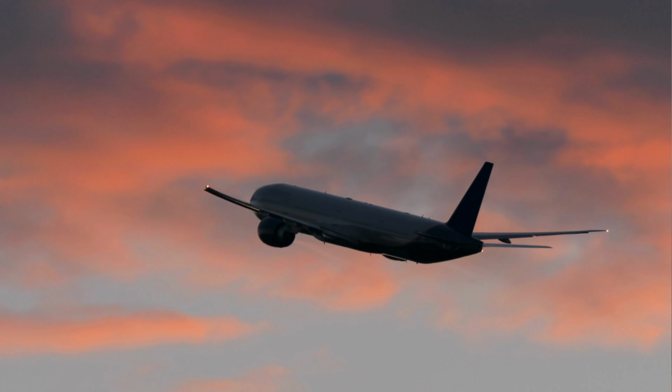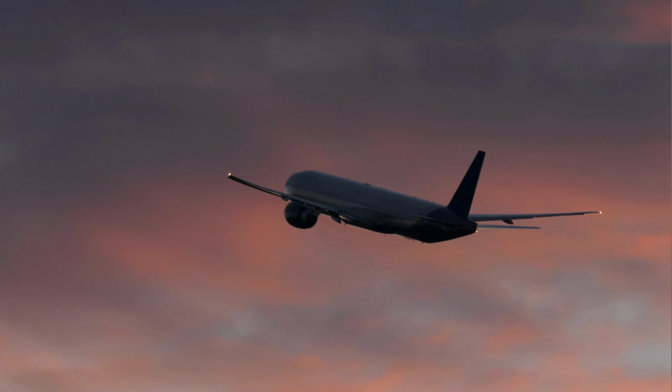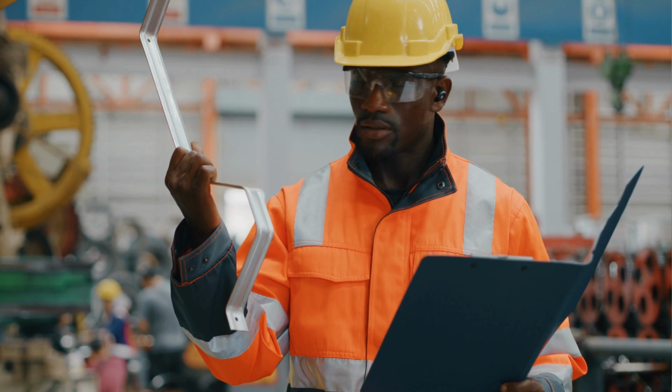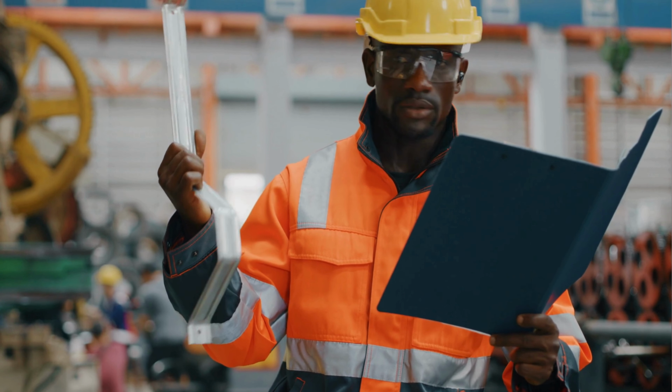But as long as you do your inspection, you verify that the storage conditions were proper, you ensure that you have the proper paperwork, you're good to go. Basically the part is airworthy. And actually you might even find at times some of these parts are more than 10 years old. But check your part, check the conditions, check the paperwork, and it's a thumbs up. That's NS. Finally, let's look at NE.